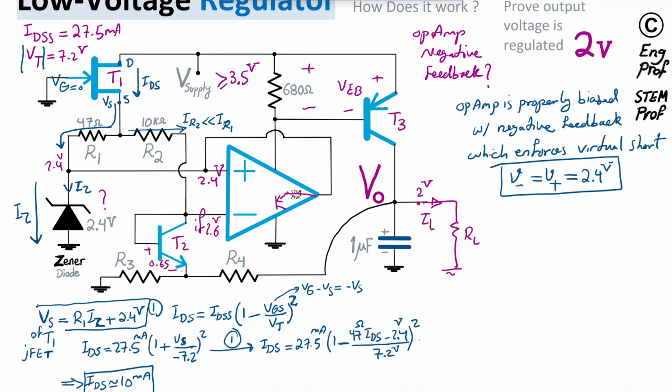Okay, so we have 10 milliamp going through this circuit here, which is more than enough to make sure that the Zener diode is very properly biased. As I said, the OpAmp is a low current OpAmp, so we don't expect much in terms of the current providing capability of this OpAmp. The PNP BJT high current transistor is the one that provides the main current at the output.